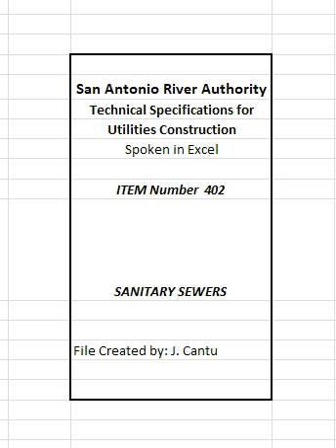No pipe shall be laid within 10 feet of any point where excavation is in progress. Pipe laying shall proceed upgrade with the tongue or spigot pointing in the direction of flow. Pipe shall be lowered into the trench without disturbing the prepared foundation or the trench sides. The drilling of lifting holes in the field will not be permitted. Pipe shall be pulled home in a straight line with all parts of the pipe on line and grade at all times. No side movement or up and down movement of the pipe will be permitted during or after the pulling operation.